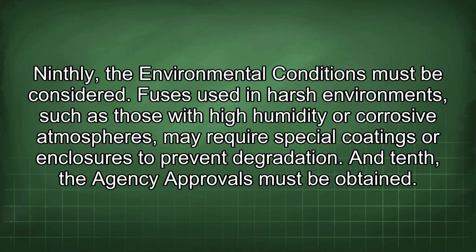Ninthly, the environmental conditions must be considered. Fuses used in harsh environments, such as those with high humidity or corrosive atmospheres, may require special coatings or enclosures to prevent degradation. And 10th, the agency approvals must be obtained.